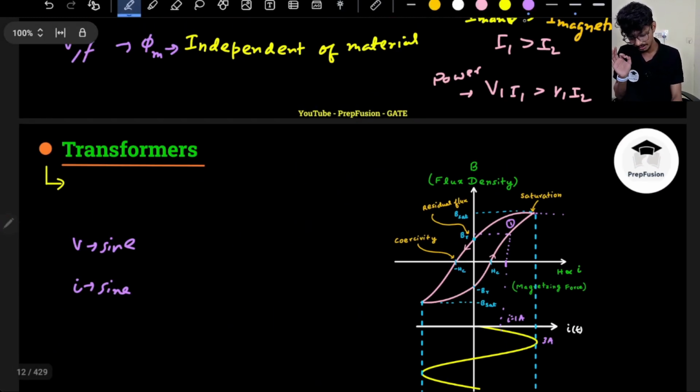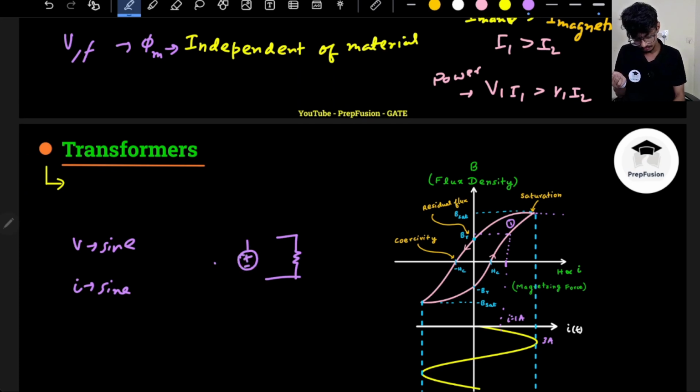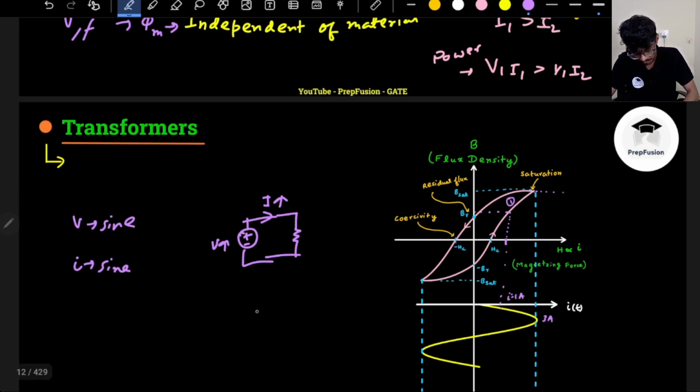Just like, if I have a resistor here and a voltage source, let's say V, and I keep on increasing this V, the current will keep on increasing, no problem. But in real life, you know that you actually will not be able to do it. Why? Because whenever you go to the market and say, I need a 1 ohm resistor, the first question the shopkeeper will ask you is, what is the wattage rating of the resistor that you want?